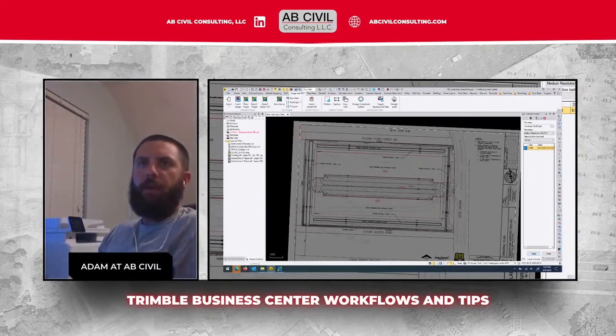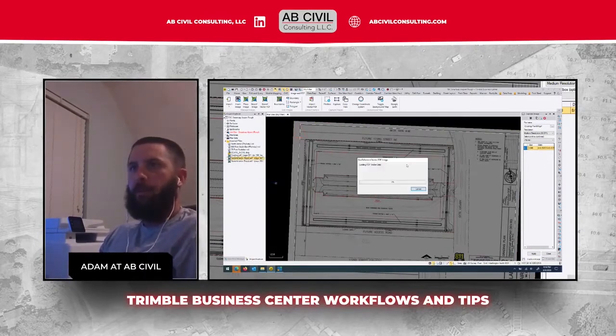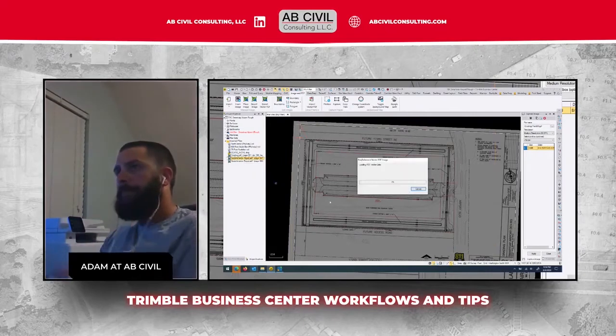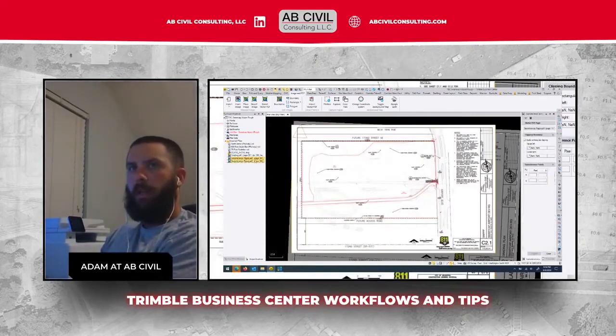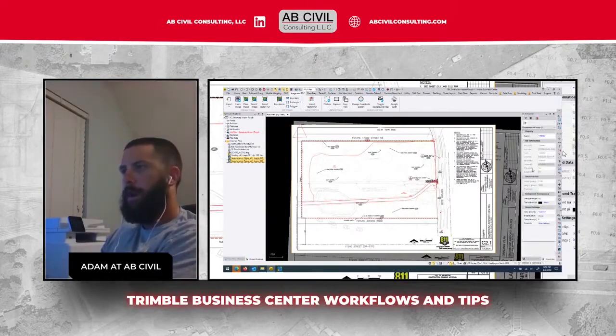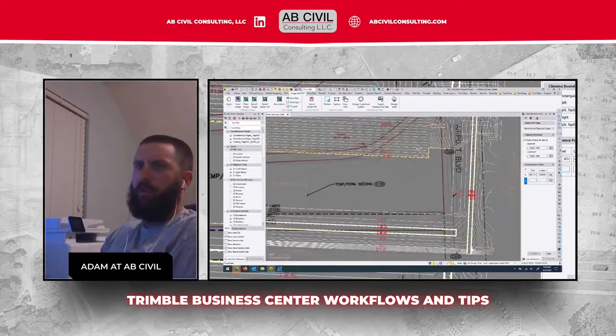So some of the missing steps if you joined late: this didn't work when I exported the image. I just geo-referenced a couple of these PDFs. Always highlight them in Project Explorer down here. Highlight the PDFs, go to Properties, and then I always change them to dimmed. I didn't bring all the line work in. This job was separate CAD files.